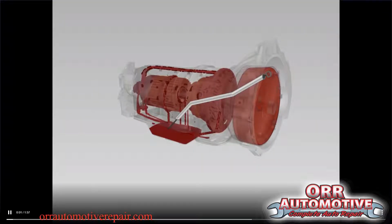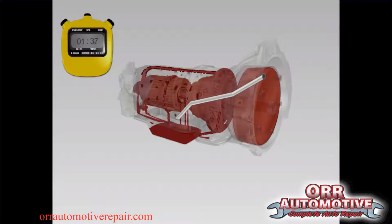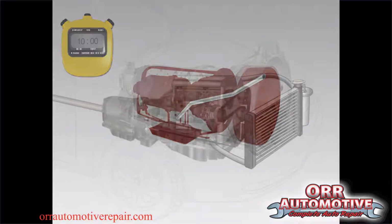As transmission fluid ages, oxidation occurs, and acids, varnish, and sludge are formed inside the transmission. Before a transmission fluid service is performed, a chemical solvent may be added to the transmission to clean varnish and sludge deposits. When the chemical is added, the sludge and varnish are dissolved into the fluid and then removed from the transmission when the fluid is replaced. Transmission fluid replacement can be performed either as a drain and fill service or by using a fluid replacement machine.